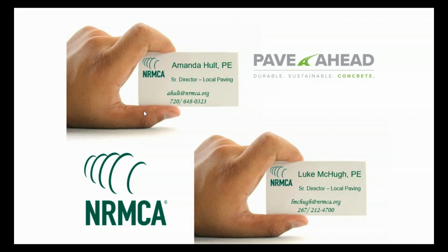All right, Brian, stay on board for this next one because I know that you and I have had this discussion. Proper external curing of CRCP, JPCP pavements has always been a major challenge out in the field. I've heard about internal curing technology where pre-saturated lightweight material is used as the carrier to provide water to hydrate the cement after initial set, thus lowering early age shrinkage and cracking.